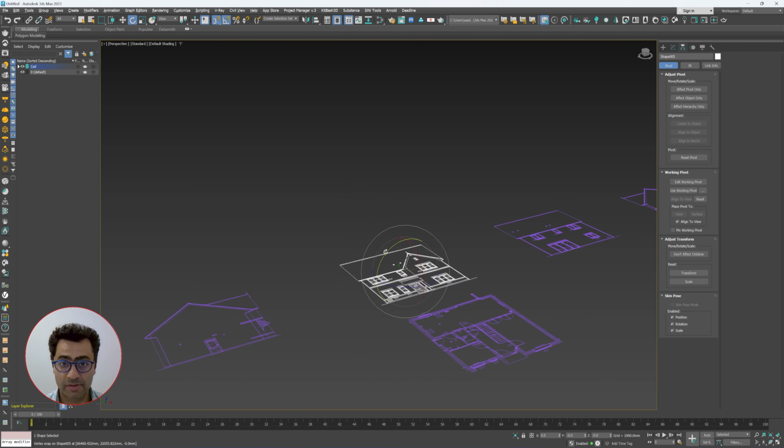So the way to do that is, for example, if I press A, I can enable the 5 unit snap. So you can easily toggle it on and off here. It's called angle snap toggle. So that's very, very helpful in order to keep everything accurate.